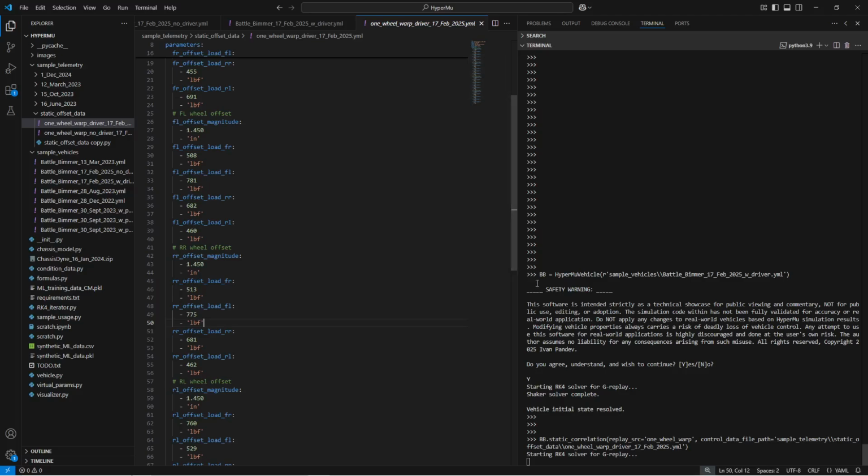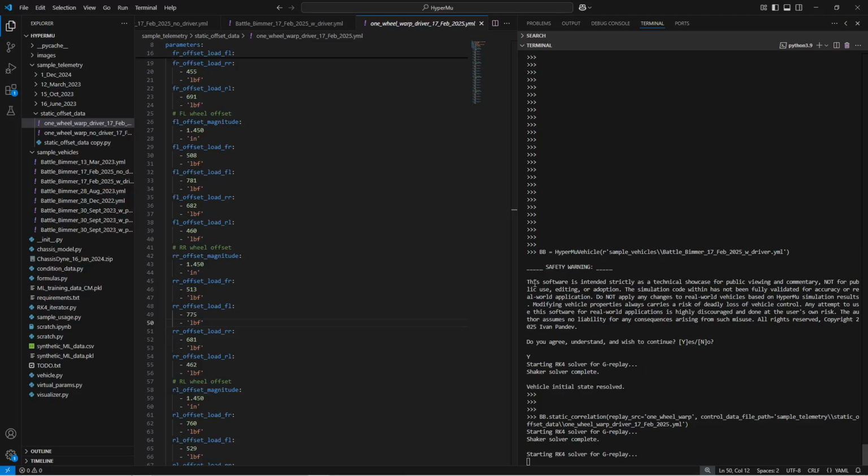As the simulator begins, the visualization will guide us through the results and the errors. You'll notice the simulation being started 4 times. Each time represents one wheel being displaced, the chassis being given time to settle, and the final weight transfers recorded.